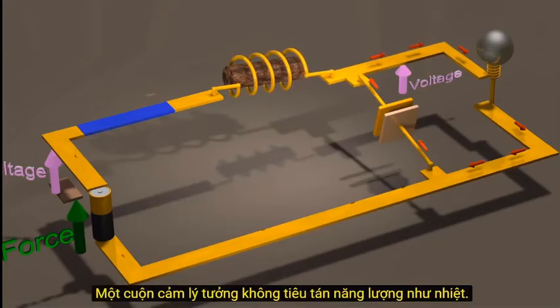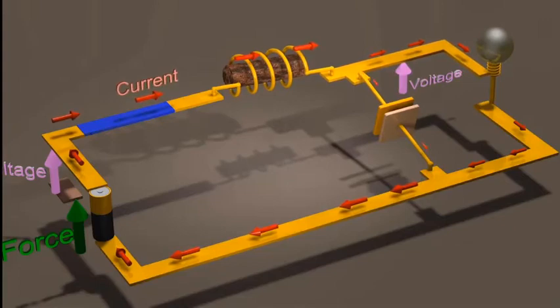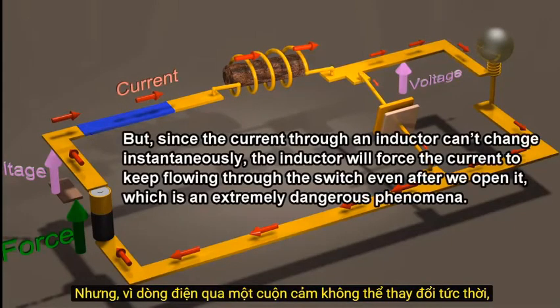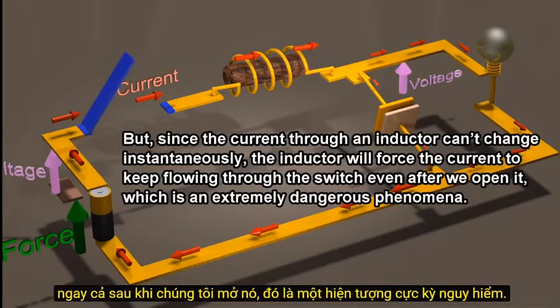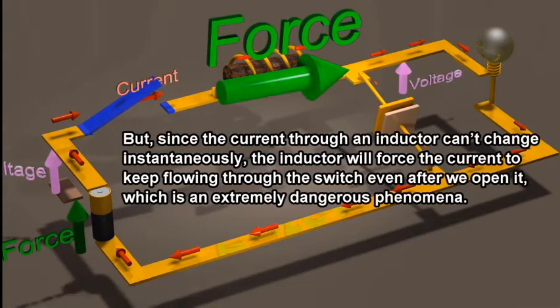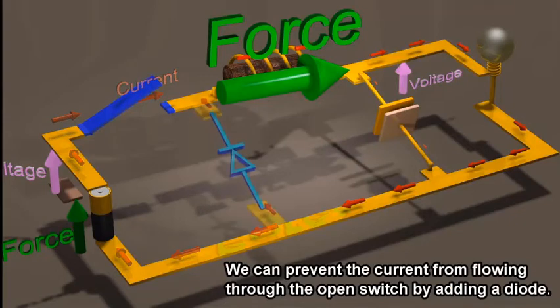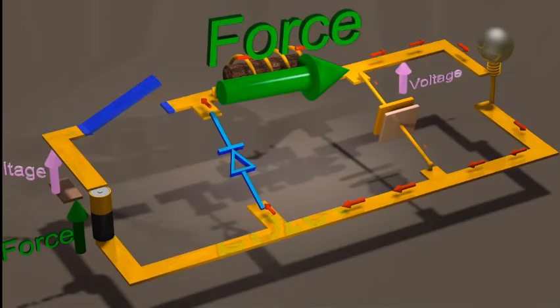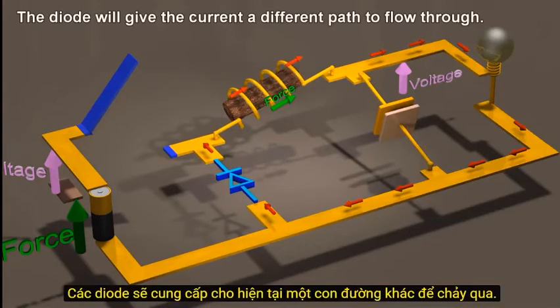An ideal inductor does not dissipate energy as heat. But since the current through an inductor can't change instantaneously, the inductor will force the current to keep flowing through the switch even after we open it, which is an extremely dangerous phenomenon. We can prevent the current from flowing through the open switch by adding a diode. The diode will give the current a different path to flow through.